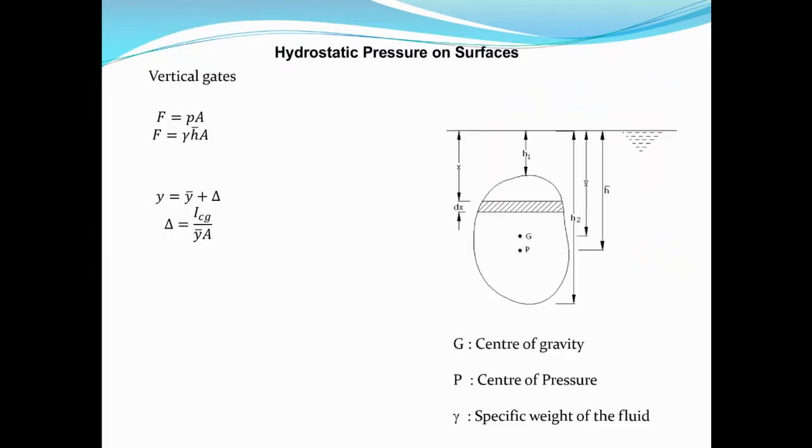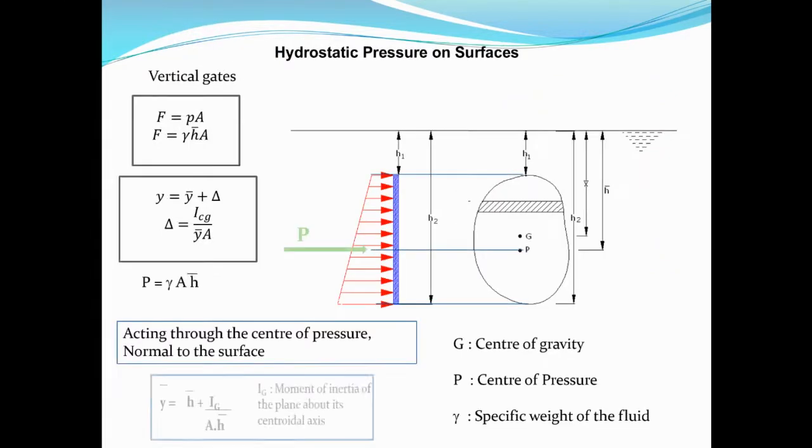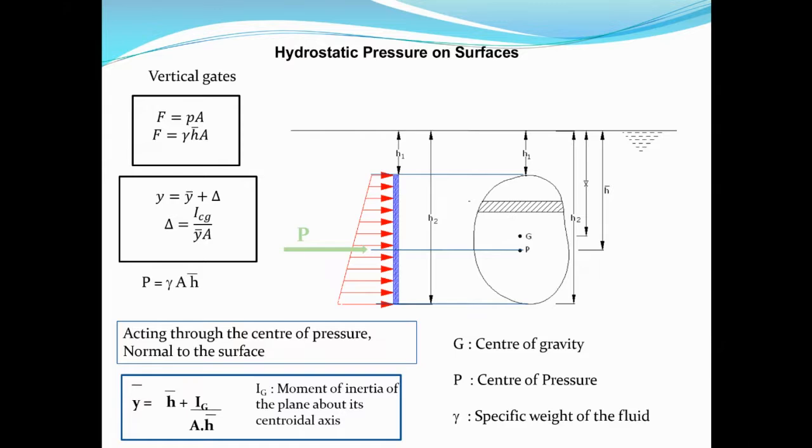Now, still on the hydrostatic pressure force, like I said, I already explained. Now we don't have sine alpha, isn't it? In the previous instance, when it is inclined, we have gamma y bar A sine theta or sine alpha. But now, because it is vertical, there is no need to have any alpha. This is the centroid, the center of gravity, and this is the center of pressure. Okay. So for vertical and inclined, the center of pressure is below the centroid.